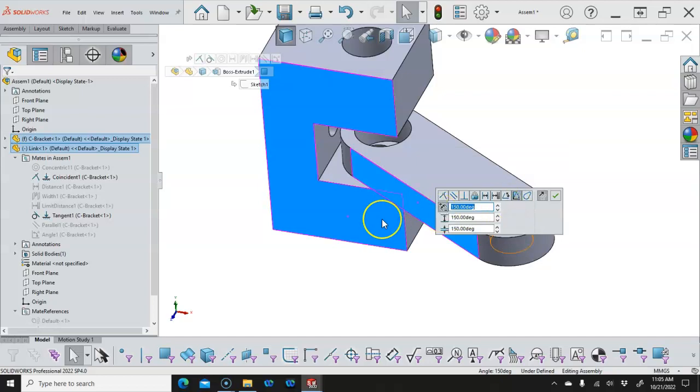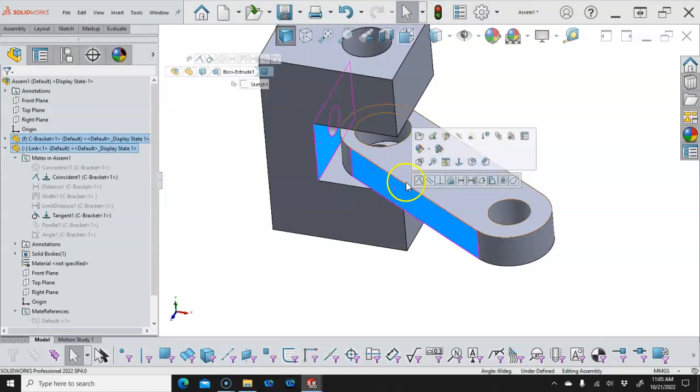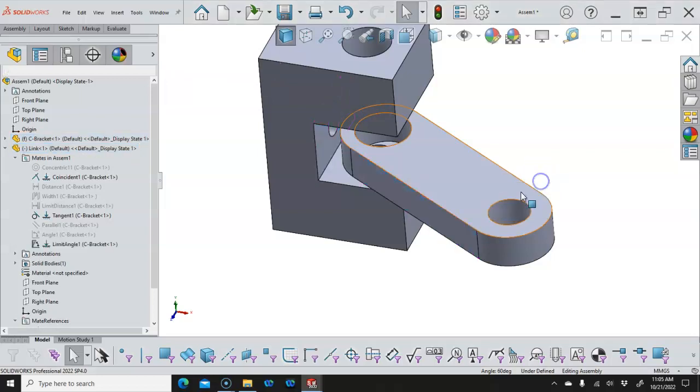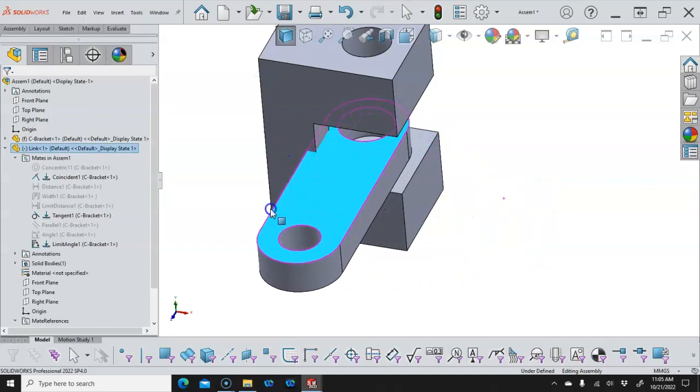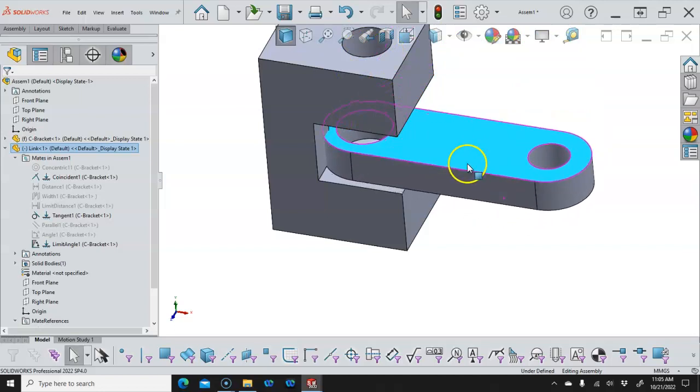The limit angle says between that face, and we kind of want to pick a face, make a selection a little bit better. This one's going to be 0 degrees to 90 degrees. If I were to go from the inside face, then set the limit angle from 0. Oh, current is 120. So if I were to set it from 180 on the max, and I try to keep the numbers consistent, and to 0, then that will give it a range, even with the tangency and the interference, that it won't move past that face in those directions.